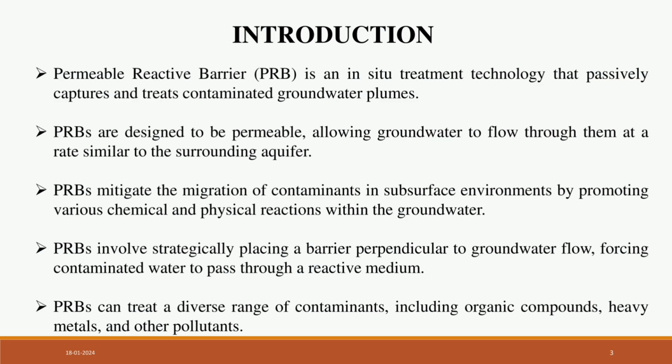The first question that comes to your mind: what is PRB? PRB is an in-situ treatment technology that passively captures and treats contaminated groundwater plumes. They are designed to be permeable so that groundwater can flow through them at a similar rate to the surrounding aquifer. PRBs mitigate the migration of contaminants in the subsurface environment by promoting various chemical and physical reactions within the groundwater.